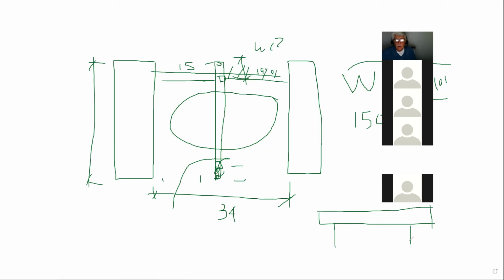Then I said, in the wintertime, when you store your equipment, do you need to circulate? He says, no. Well, in that case, why don't you put a column in here only for the wintertime? You see? What about in the summer? In the summertime, you can take it off. And in the summertime, the beam was good for 20 pounds per square foot, because there's no snow. Exactly. Okay, got it.